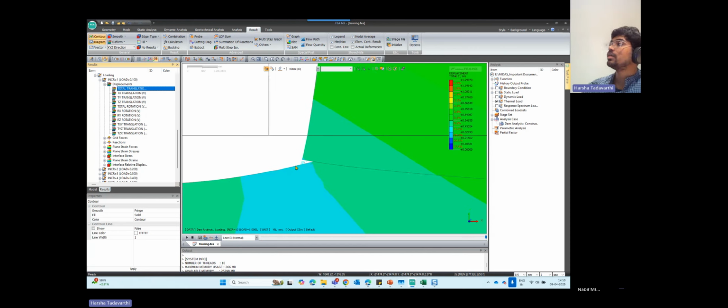Had it been a ULS load, then it might be a much more deformed location. You might see much higher movement, not just one element over here, even multiple elements might have failed. So right now, one interface element has failed under tension, since the tension reached the limit of 0 when a tension crack started getting generated here.